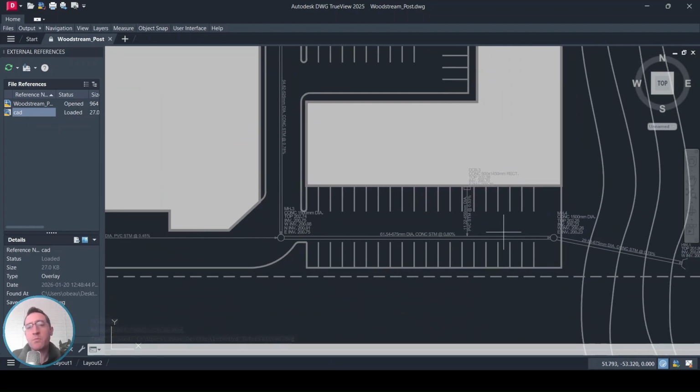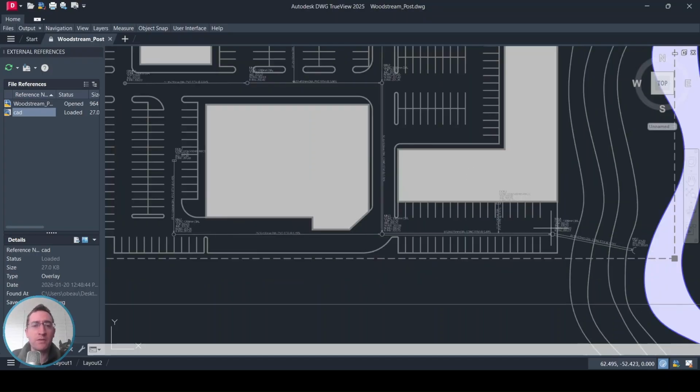This is why it's super important when you're starting a new project for the first time, you make sure that the background image is coming in at the correct location. I typically recommend you load the background image, you just do a quick test with a couple conduits, export it back to AutoCAD, and just make sure everything is appearing in the correct spot.